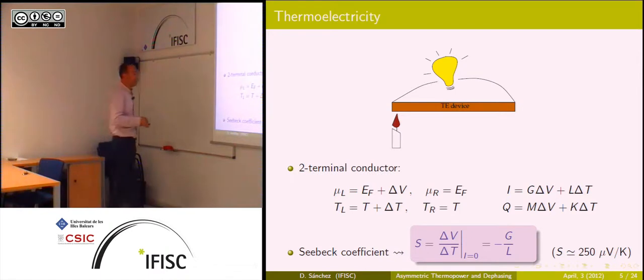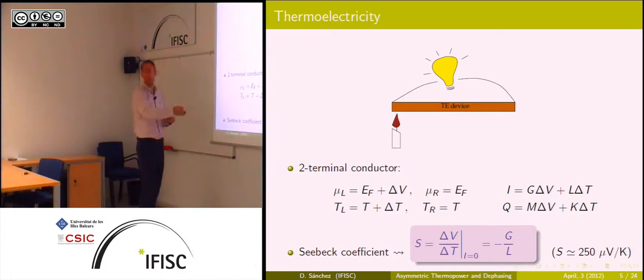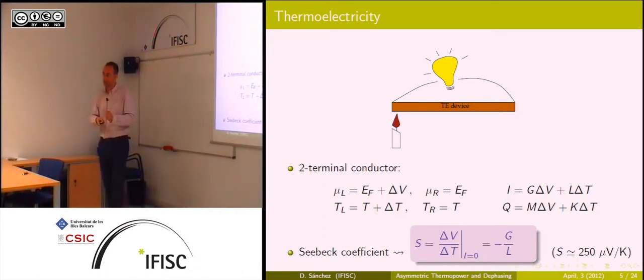The Seebeck coefficient is defined in such a way that, as I said before, the conditions are open circuit. So there is no current flowing through the sample, so you put here 0, and then the voltage generated between the sides of the conductor divided by the temperature difference that you are applying, at the condition of zero net current, that's the Seebeck coefficient.